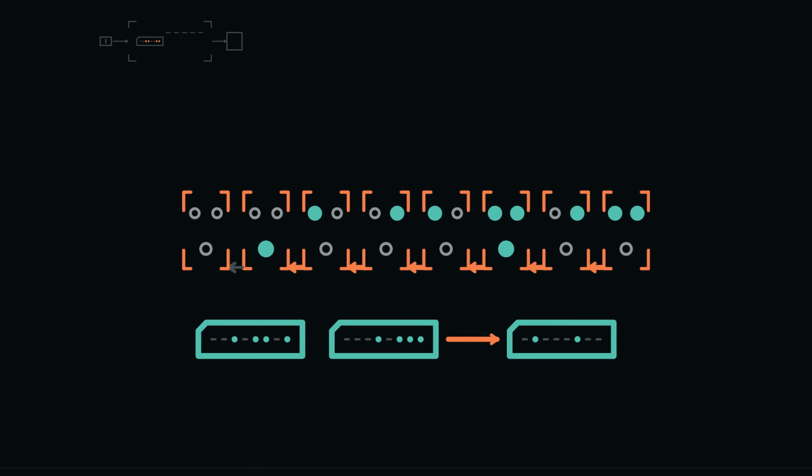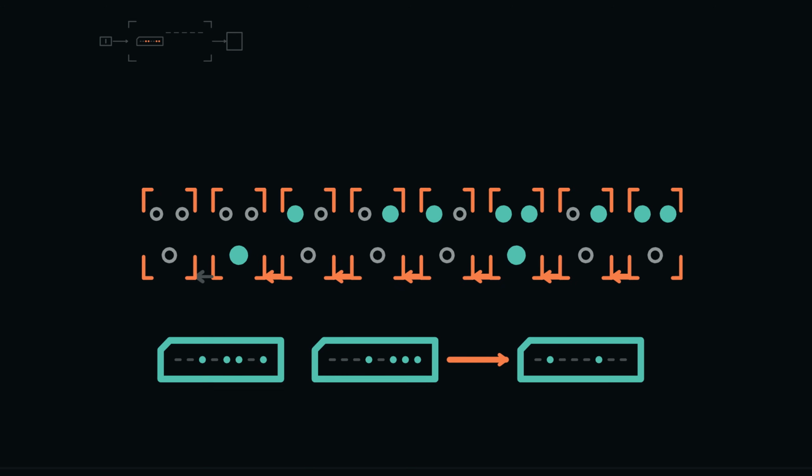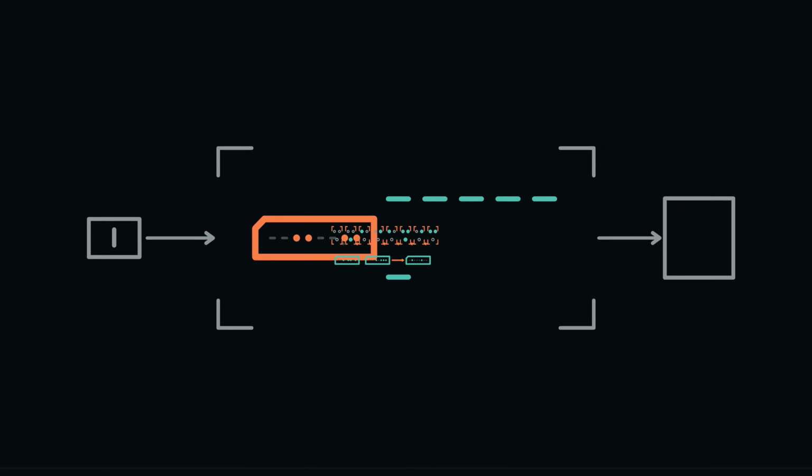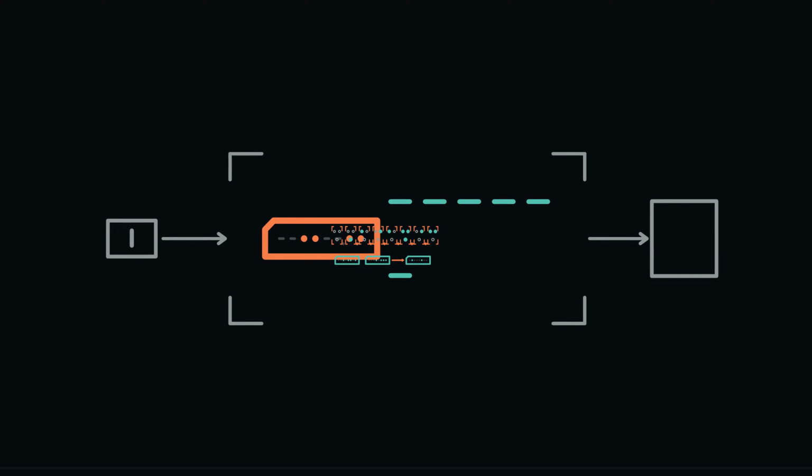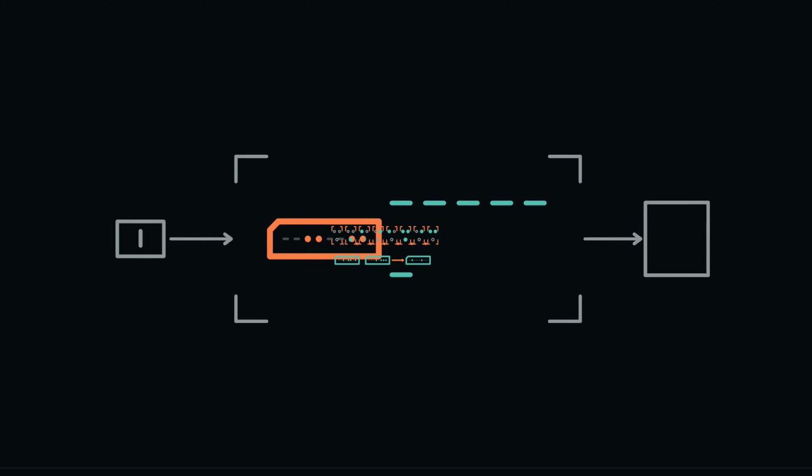Compress the 8 cells into an adder module only after preserving its inspectable seams. 2 8-bit operands enter. Carry begins at bit 0 and links each position to the next. 8 sum bits and a final carry emerge after settling. The module has no memory of its own. Changing an input can change its outputs until a destination register captures at an edge.